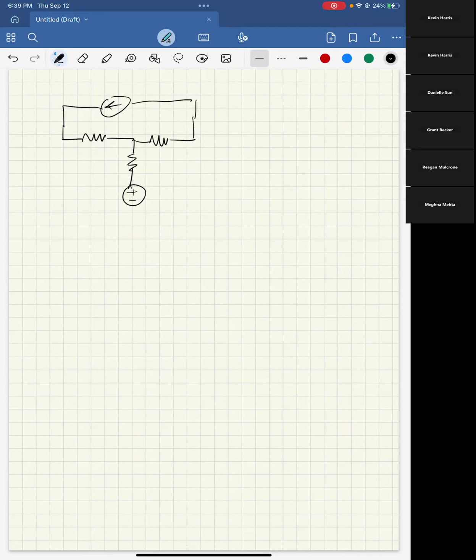But mesh current is pretty similar to node voltage in that you are using these things you name to make 3 equations that relate different quantities together, and then you use those equations to solve for the values you want. On the homeworks, of course, once you get your equations, you can just plug them into an equation solver, and it works just as well. Always good to practice doing algebra, as you do not have access to an equation solver during an exam.